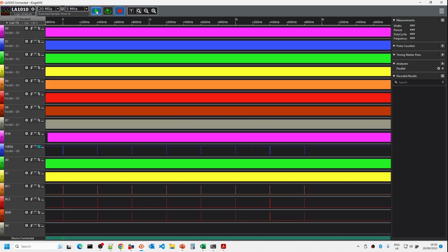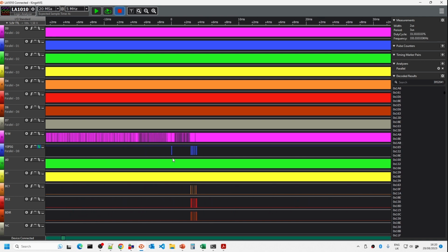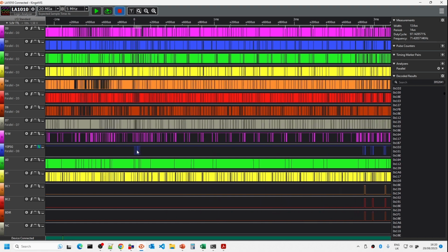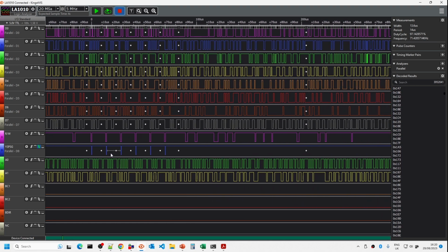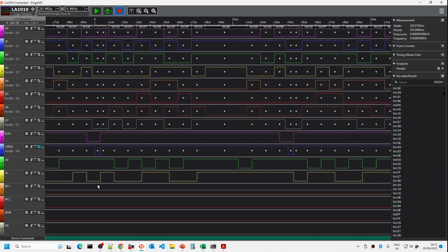Okay, so that seems to work. And if we have a look here, what we can see on the logic analyzer output is the programmable sound generator chip select here. If we drill down into this, what I've got is the data lines going into the PIA, the read-write signal, and then whenever we're enabling the PIA, this is how we can tell what's going on there. And then we can tell which register's been written on the PIA between the A0 and the A1 signal.